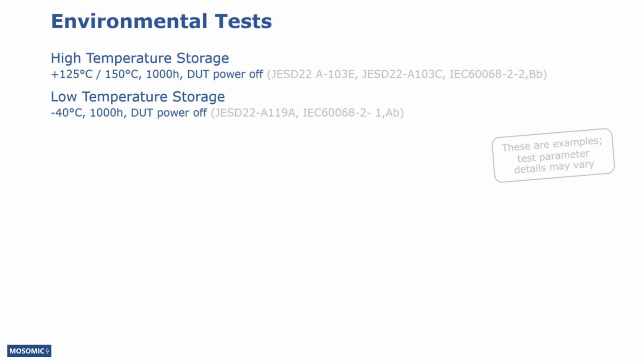The duration of each test can range from 72 hours to 1000 hours. In a 1000-hour test, there may be intermediate checkpoints to see how the microphones are doing, for example at 168 and 500 hours. Without intermediate checks, we wouldn't know whether the microphone failed at 1 hour or 950 hours. Since these are storage tests, the microphones are not powered on during the tests.